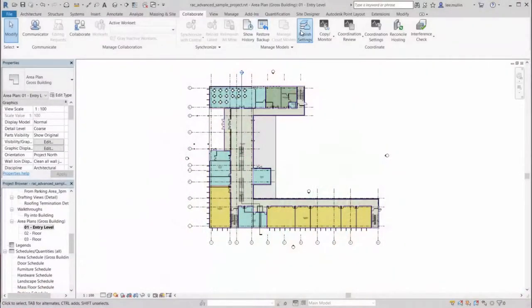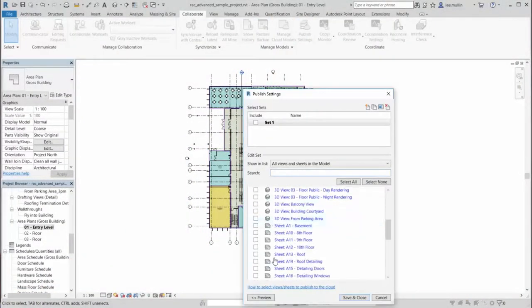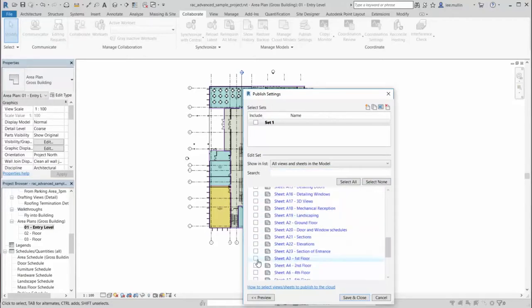Now, as I said, in Collaboration for Revit, this is a byproduct which comes automatically, which is offered by Collaboration for Revit. We just simply check the sheets that we need published. It is being stored in the Revit file. It's visible in BIM 360 Team. We don't need to send out anything anymore.